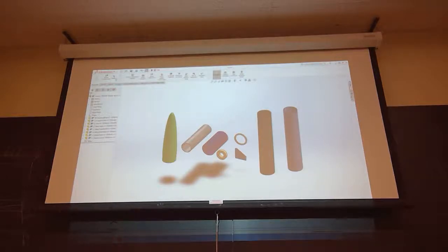So you see mate is here, insert components here. If you realize you're missing a component or something, you just go ahead and click insert components, and it'll bring us to the same thing that we saw before. But we're done with that, so I'm going to hit cancel. Now we have mate. It has a good definition: positions two components relative to one another. And that's pretty much how we're going to be assembling this entire piece.